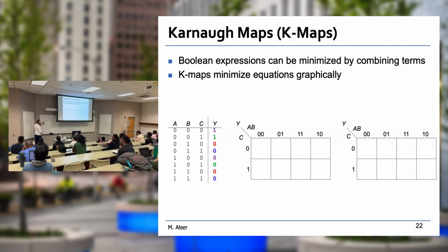Now, what are the first ones? Those 2. Those are the second ones. Okay. So now we want to build this huge Karnaugh map. Please remember how we draw it. We had this line over here, and then we said these first ones will go here, ST, and the others will go here. Remember to keep the exact same order so we can match it with the truth table. Then it's easy for us to fill this from the truth table. If you make any mistake here, if you swap them, then it's still correct, but you really need to go line by line and try to figure out where the value is. Now, we split this into 4 because we have 2 variables. They have 4 permutations, so we need 4 boxes. Likewise in here, we have 2 variables, 4 permutations, so we need to split it into 4 boxes.